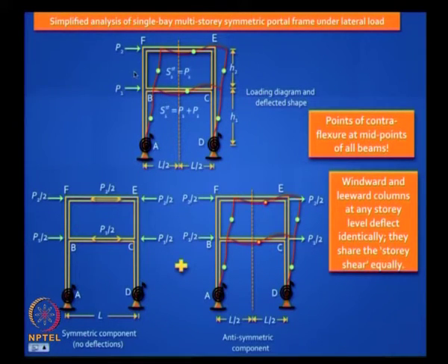Now let us say I cut a section here, wherever the hinge locations are in the columns, and I take out the top part, then it is like a cantilever, it is taking some lateral load, that is referred to as a story shear. Look at the word, story shear is the lateral load taken by all the columns in one story.